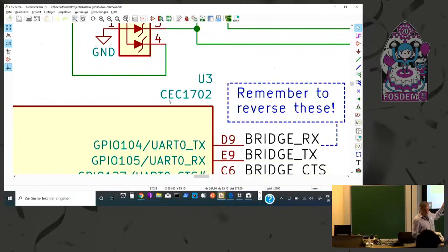Now, the source code is actually in the bootloader. I can't remember, the architecture of the CEC 1702 is a bit strange, but they have a very good method of encrypting the firmware, even if it's off chip, if it's on SQI flash or something like that. And you can implement very nice secure boot using the CEC 1702. So that's one alternative that I can suggest in the few seconds.